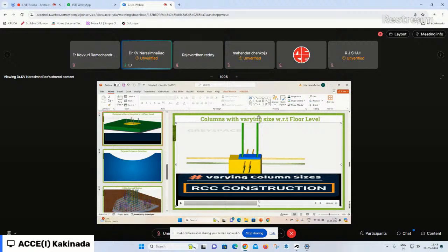From the design point of view also, we have to consider this eccentricity whenever we are planning the reinforcement in this pattern, and it should also be taken during the design stage. During the detailing stage, one more important point is that it is better for the bars in the bottom stage to continue into the top steel, as a standard detailing practice.